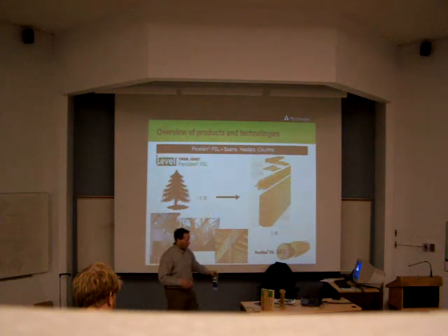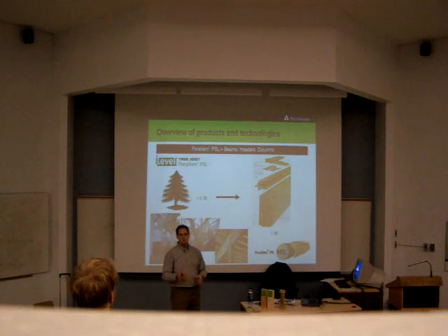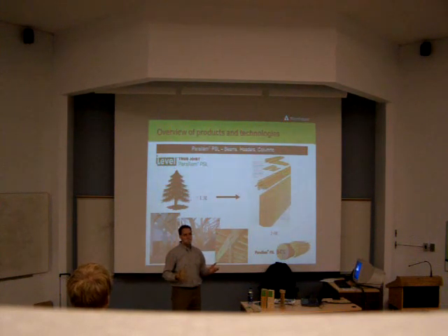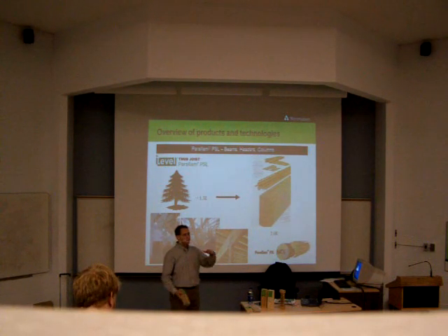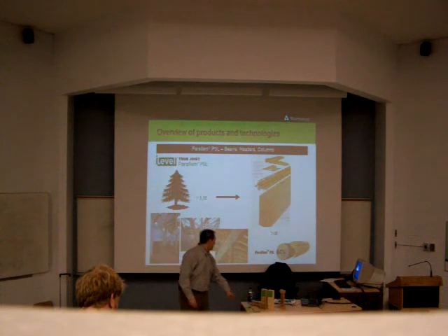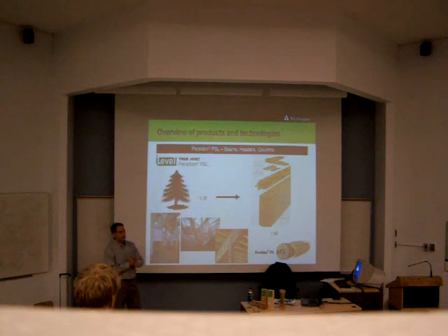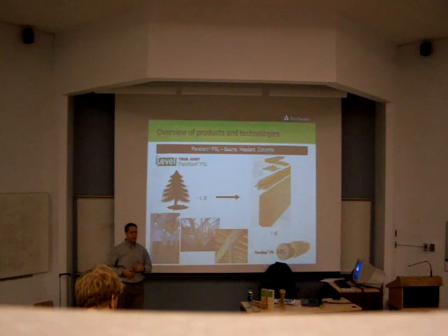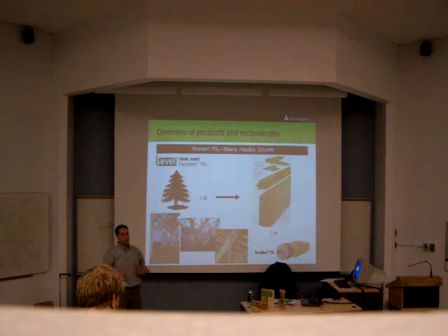Okay, and what's unique about Parallam is that we can press it into very large billets. So we commonly see beams up to 7 inches wide by 18 3/4 inches deep. So real big, heavy, solid pieces of lumber. And we run into that a lot in post and beam or real architectural type stuff. A lot of architects and engineers like that. It's very similar in terms of strength and fire performance and all of that to heavy timber, to old growth heavy timber, but it's obviously much more readily available.